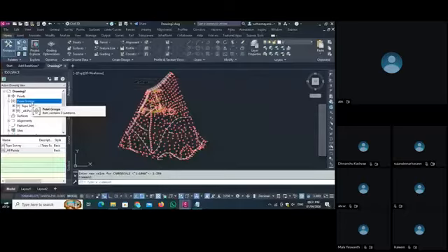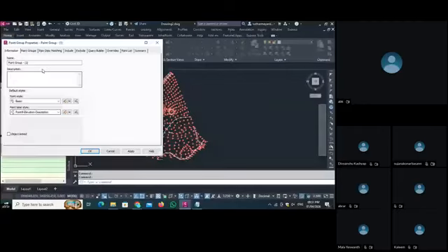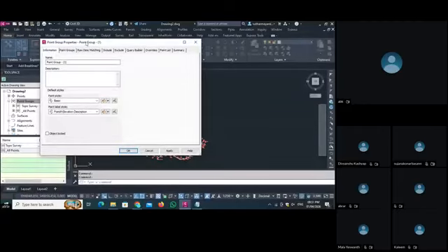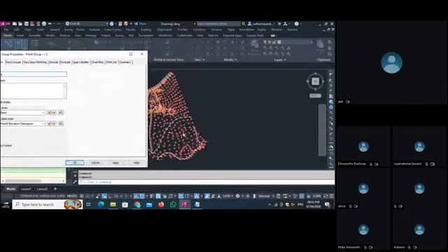The second thing, if you want to create a new group, you have to go here to New. As you click New, you get this Point Group Properties. In the Information tab, there is a name. You have to provide a name. First of all, I am giving the name as Building. See, there is a point style and a point label style. These two are different things. Point style denotes the point in a different style, and label style is used for the label with the points.